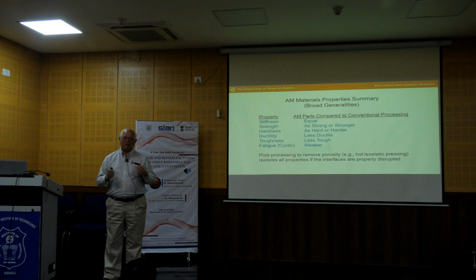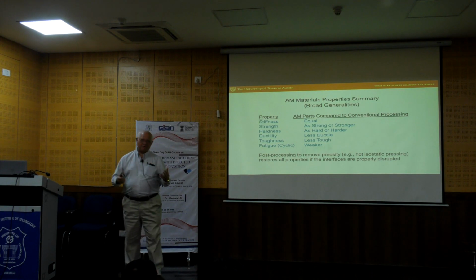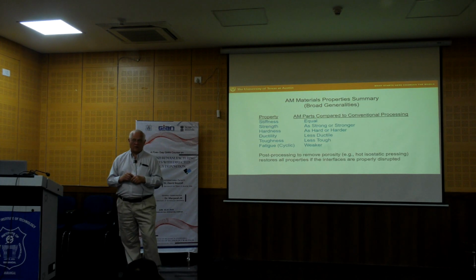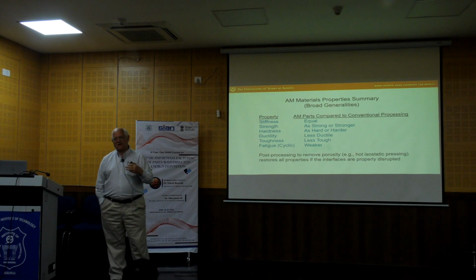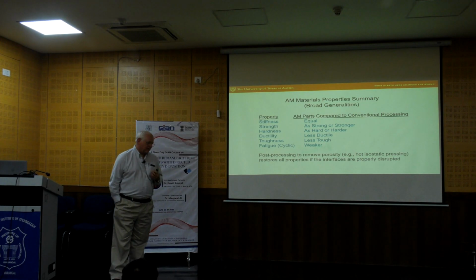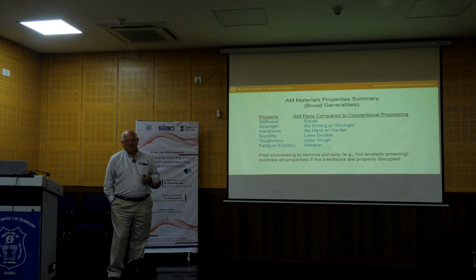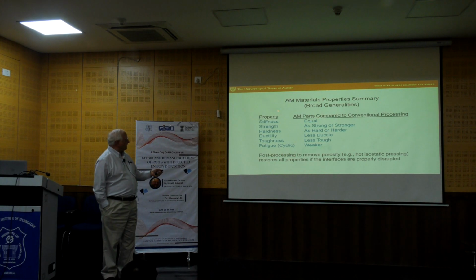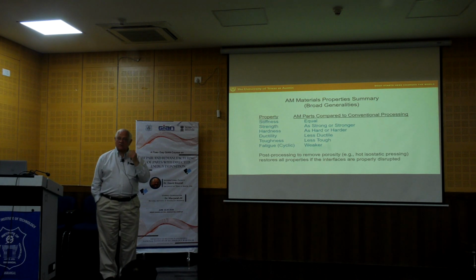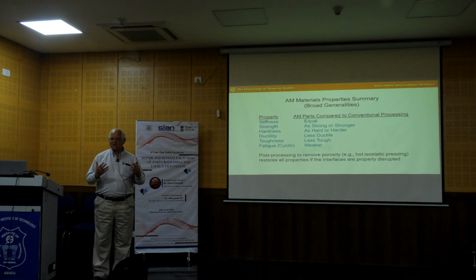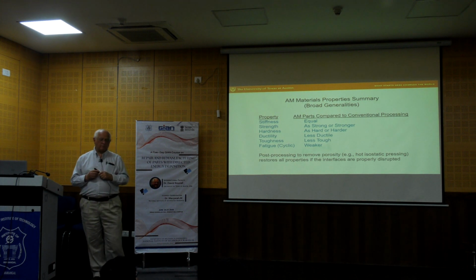So there's still something going on. Maybe there may be an increased dislocation density, perhaps, as well from the high cooling rate. The statistically necessary dislocations perhaps are higher as well. But at any rate, regardless of the mechanism, the parts that are produced by additive are stronger and harder, since hardness and strength kind of measure the same thing.